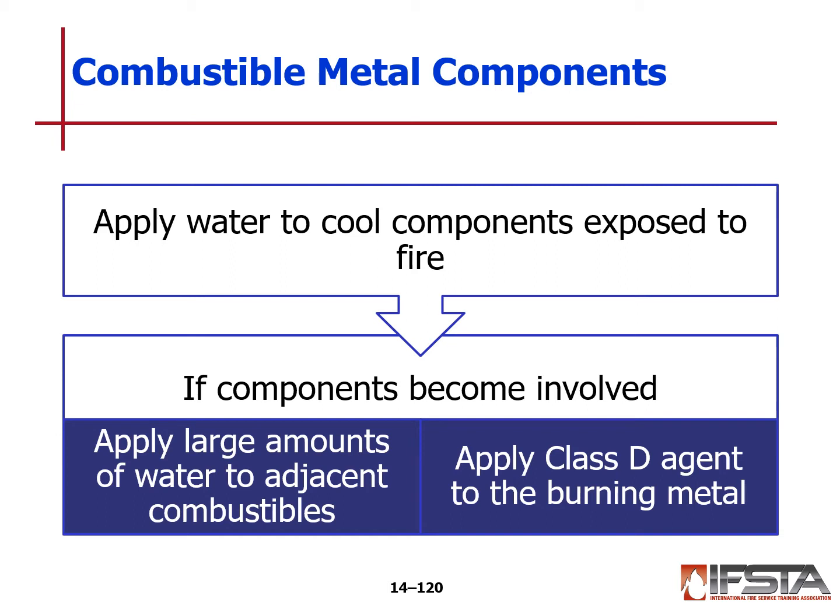Hopefully we reduce a significant amount of heat, but we have to realize that some metals react with water, such as magnesium, and at the point that they start combustion, water could be a very difficult material to use as an extinguishing agent. We may need to break out our Class D type extinguishers to get them fully put out.